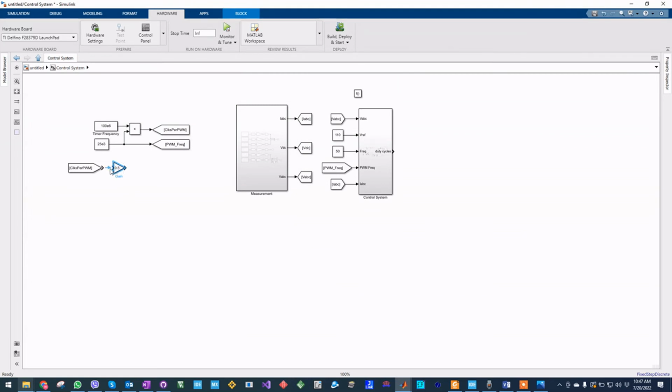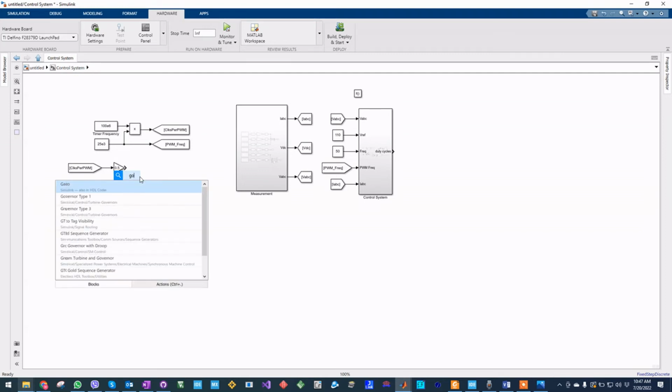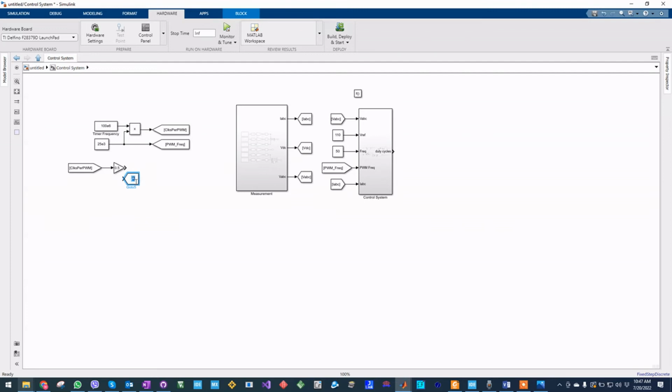Now this represents the number of ticks or the number of clocks for the timer that we have to configure the timer module to. We can name it timer period clocks. So this area right now is for the configuration of timer and timer related ticks.